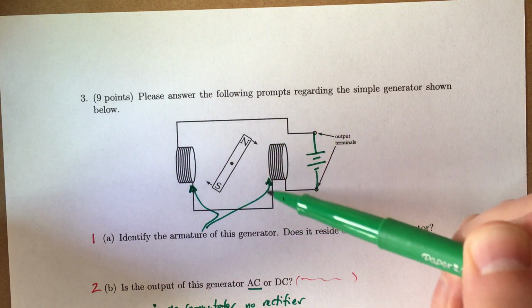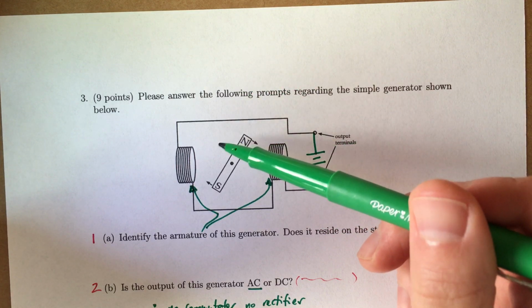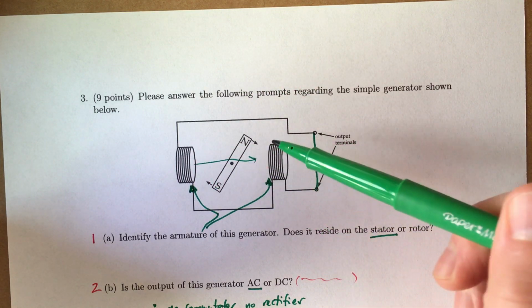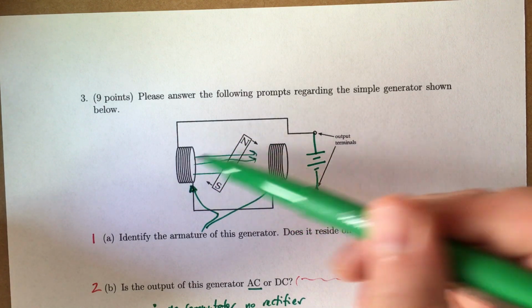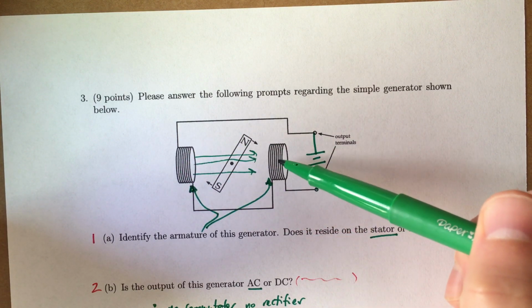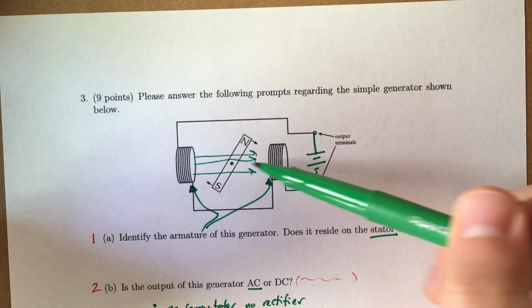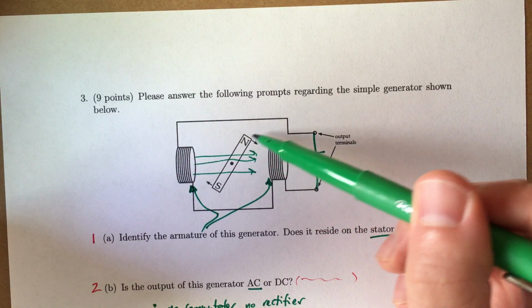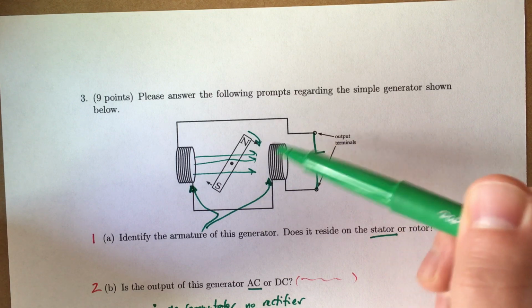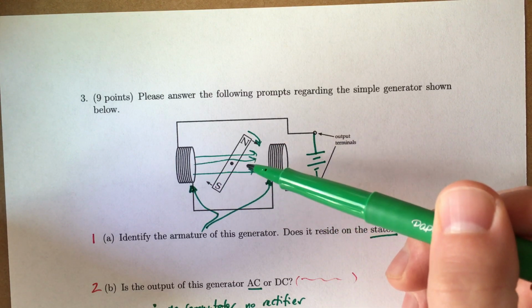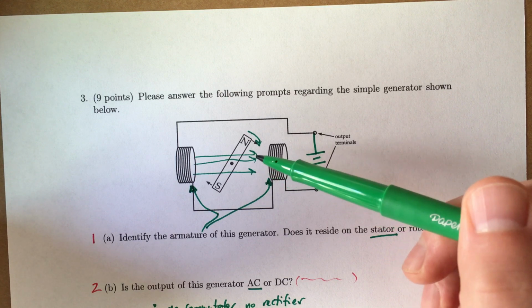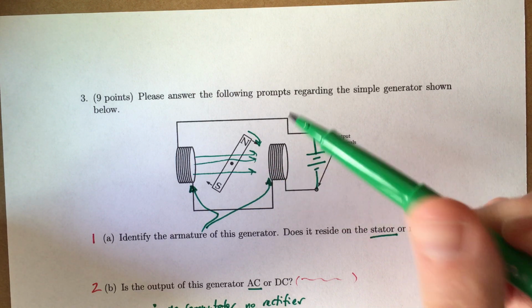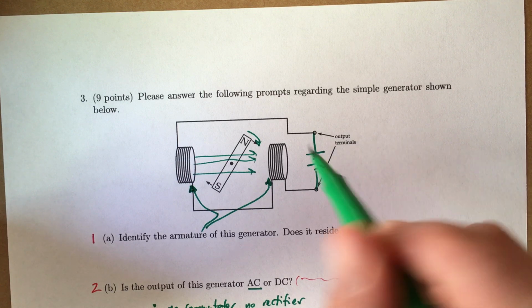The circuit's complete, but that would just create a magnetic field going this direction, depending on the direction of these windings, but still some magnetic field fixed in direction. So this rotor would turn until it aligned with that magnetic field, but then the magnetic field wouldn't change, and so the rotor would just line up like a compass needle and then be done. It wouldn't act as a motor. So this is not an option.